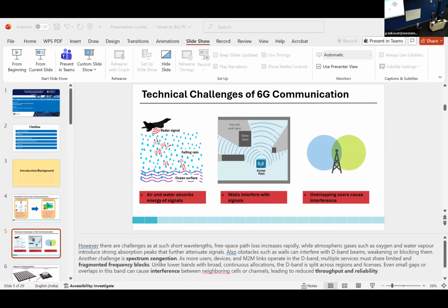And then also in the transverse magnetic polarization, a shift was found in the X band spectrum from 9.05 to 11.29 gigahertz. They also had a prototype fabricated and measured, and this shows how there was real-time tunability across the three microwave bands and polarization adaptability.